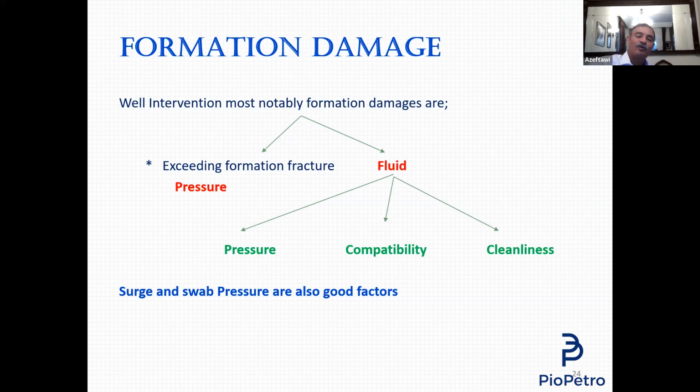Why? To minimize erosion. Because this valve, you close it in this direction, against flow coming in this direction. So this flow, if you close this slowly, it will erode the sealing part or the sealing surface of the gate valve. This is the only time, as far as I know, that I read in an API that the word quickly is the correct one, when we close the flowing valve. Rather than that, slowly, please.